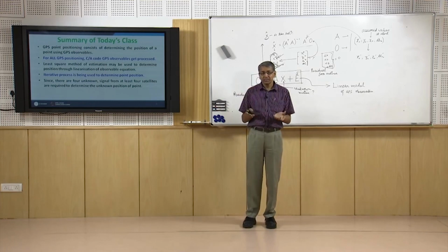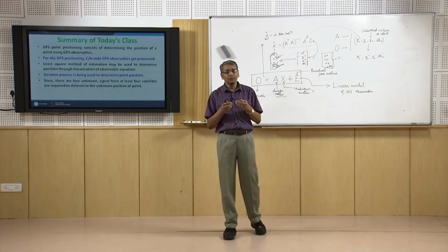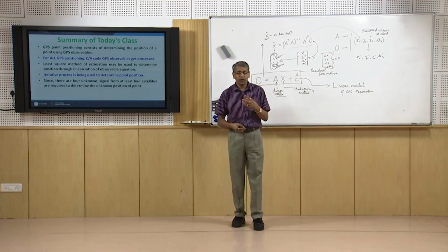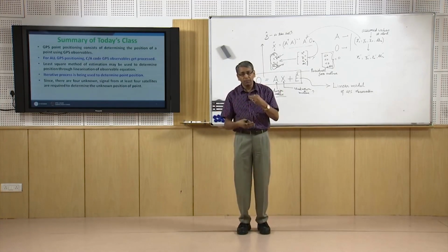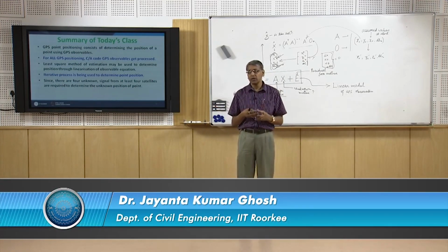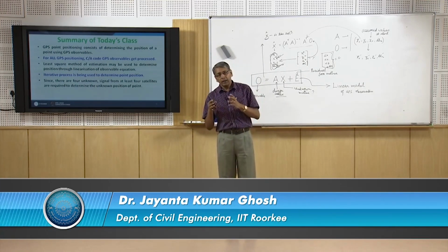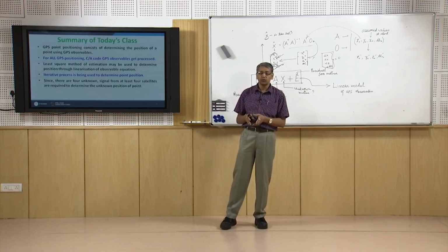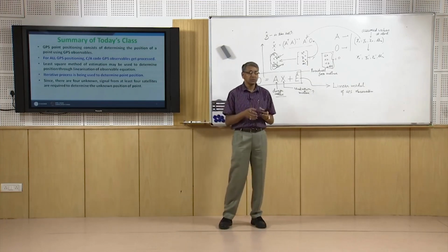During least square analysis, first we will assume a value, and from that value we will find the next approximate value, and that will be iterated sequentially, leading finally to the actual value of the position, and to arrive at the final result we need to make the parameters del x, del y, del z and del tr to be 0.